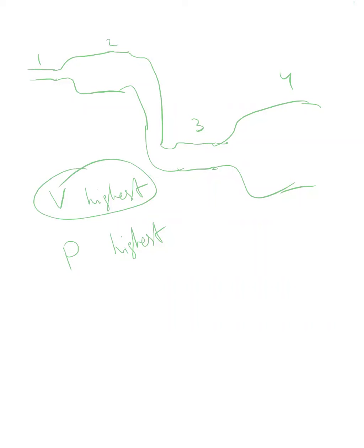This, I think, is a simple question because you don't really care about what this pipe does. The only thing that you care about is its width. We know from the first half of this lecture that since the volume is conserved, you have the fastest flow where you have the narrowest pipe, and the narrowest pipe is here in section 1. And therefore, my conclusion is that you have the highest velocity in section 1. And consequently, you have the lowest velocity, the slowest flow in section 4.